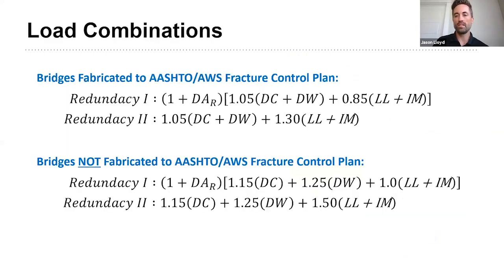A load model was developed using reliability theory. The approach used to develop the load factors is consistent with that used in the development of the existing AASHTO LRFD bridge design specification. The reliability analysis utilized the statistical parameters described in SHRP2 report entitled Bridges for 100-Year Service Beyond 100 Years, Service Limit State Design, as well as NCHRP report 368 entitled Calibration of LRFD Bridge Design Code, which was also used in the development of the AASHTO LRFD load factors.